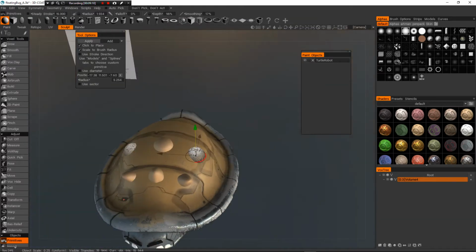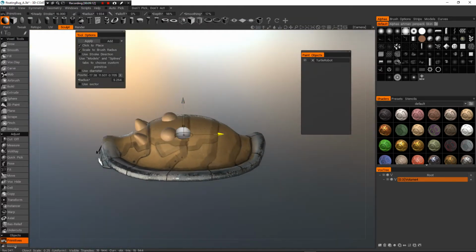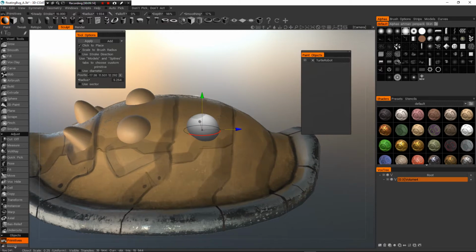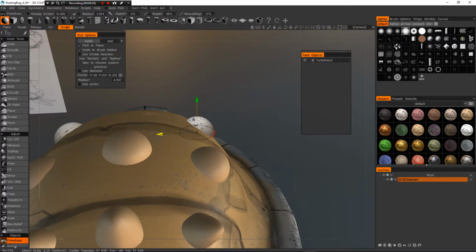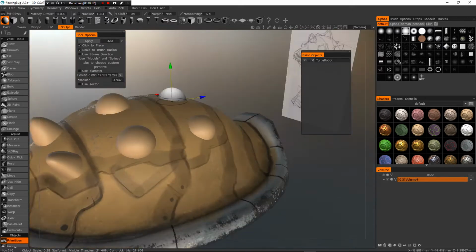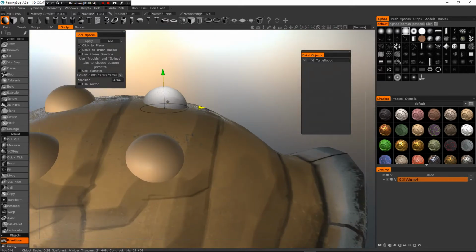Again, I'll press enter when I'm happy with the position. I'll do a couple more. So I'll move this back like so. Maybe make it a little smaller. Press enter. Move it into the center again. If I want to get it right in the center, I can see I have my X, Y, Z position. I can set the X position to 0 for more precision. Press enter.